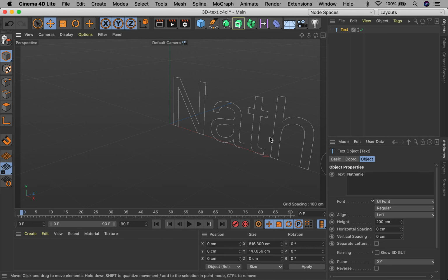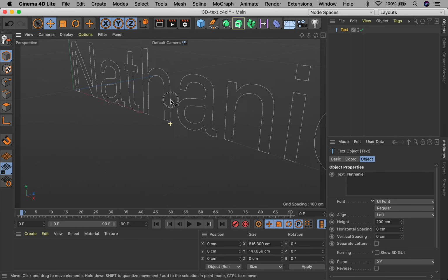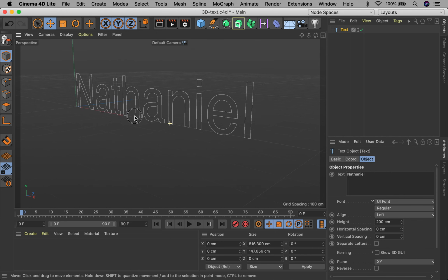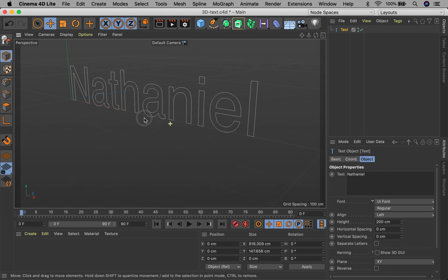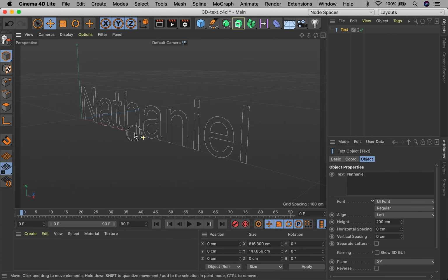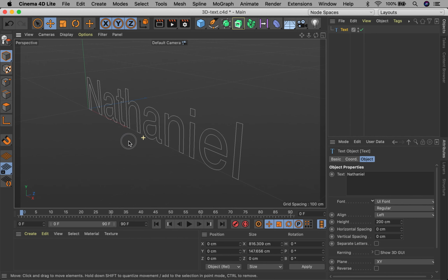So now's a good time to talk about navigation, right? If you hold down 1 and you go right to left, up, down, you can get your kind of directional navigation, right? If you hold down 2, you can zoom in and out by going up and down on your scroll pad, right? And then 3 gives you a rotation view, right? So I'm going to just adjust this so that all of it's in frame here. Okay. So kind of like looking above it like that.